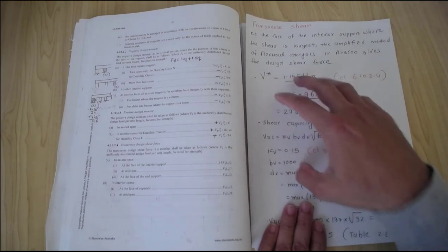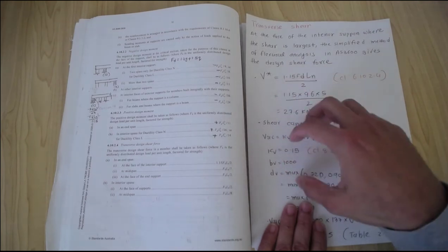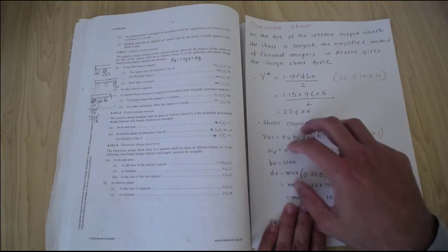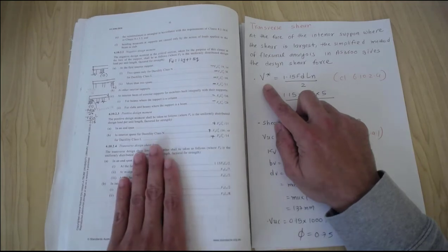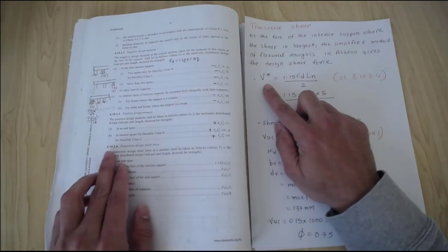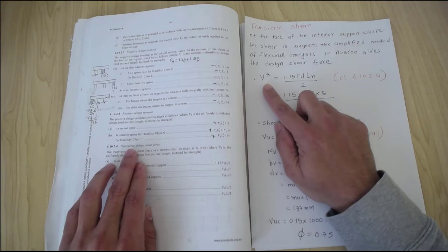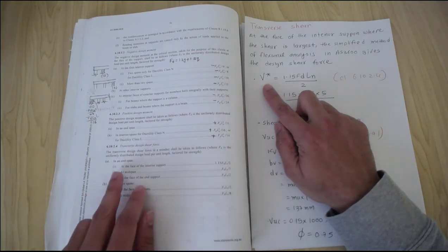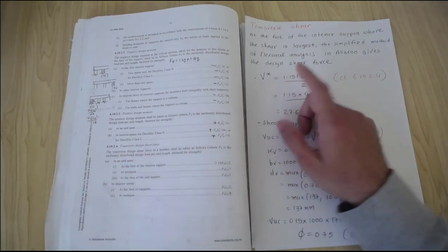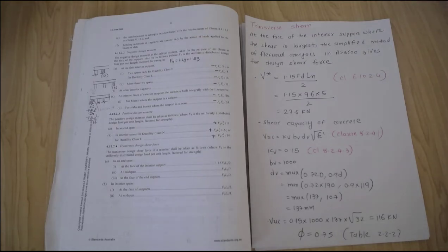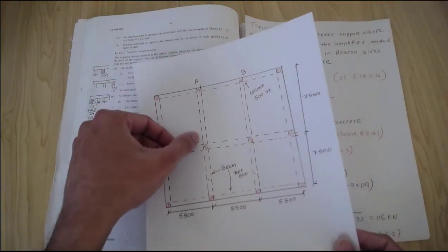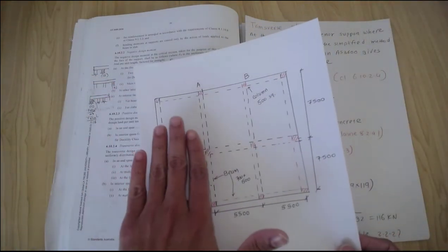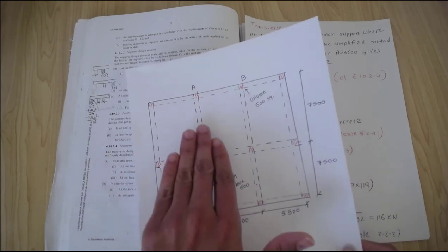We did a similar calculation in the one-way slab, so I've just quickly described the same scenario here. First of all, we need to calculate the design shear force. On page 96, clause 6.10.2.4 gives the design shear force equations. Now we are working in the end span, as shown in the drawing, at the face of the interior support. At this face of the interior support we have the maximum shear, so if you draw the shear force diagram, you will see the maximum shear here.